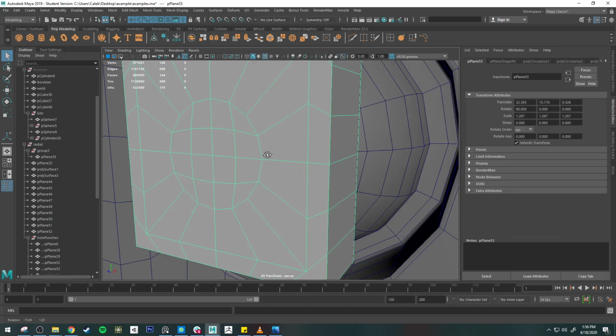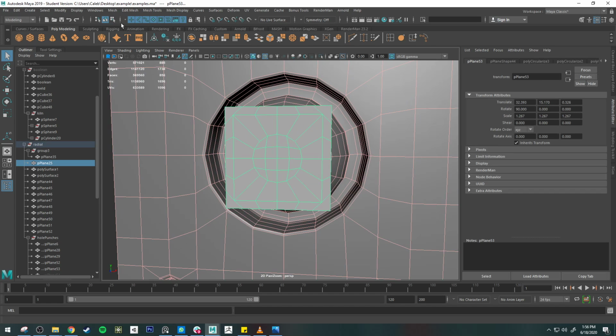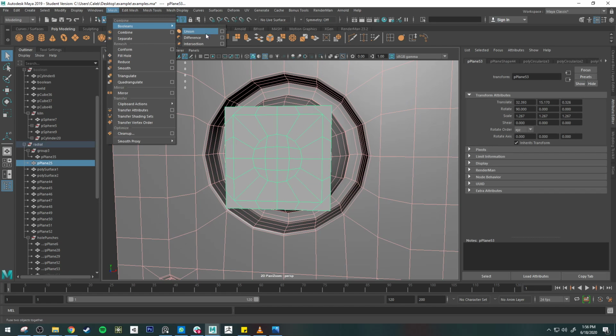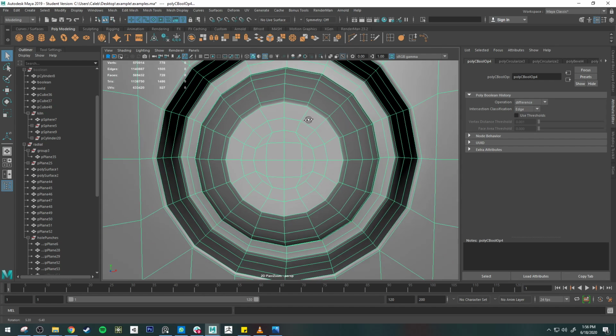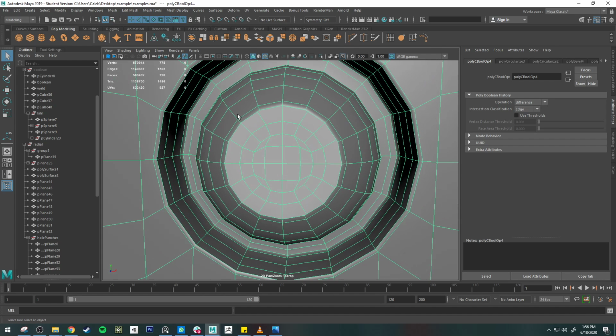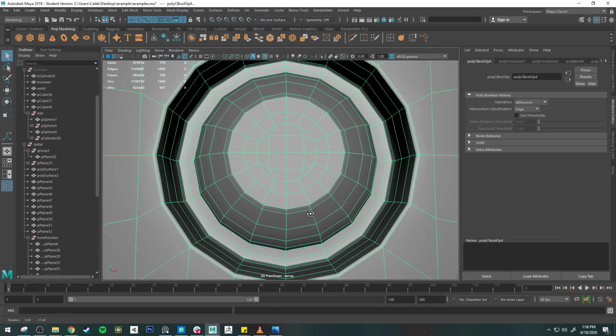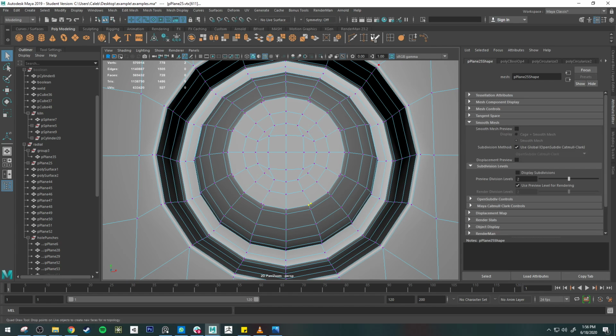Let's go back. And so we'll just take this mesh, mesh Boolean difference. And yeah, they're still not lining up, which makes me think that maybe these edges aren't actually, or maybe I have the wrong number, I'm not sure. But let's just try to start welding these guys together. So we'll go ahead and merge. All right. And it takes just a little bit of cleanup process.